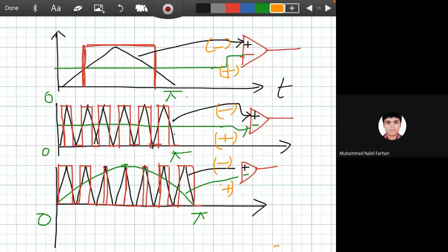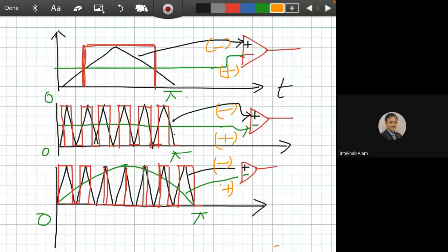Just out of curiosity, let's do it. Okay, so if you do it, then you can get some idea about how you can generate electronic signals, like this modulating output for an inverter. Actually, we do not do it using a microprocessor or microcontroller. Whenever we do it using a microprocessor or microcontroller, the controller actually remains engaged for the whole time. So actually, we use a timing circuit or some sort of timer or RAM or even a lookup table or even EEPROM to create this type of signal.